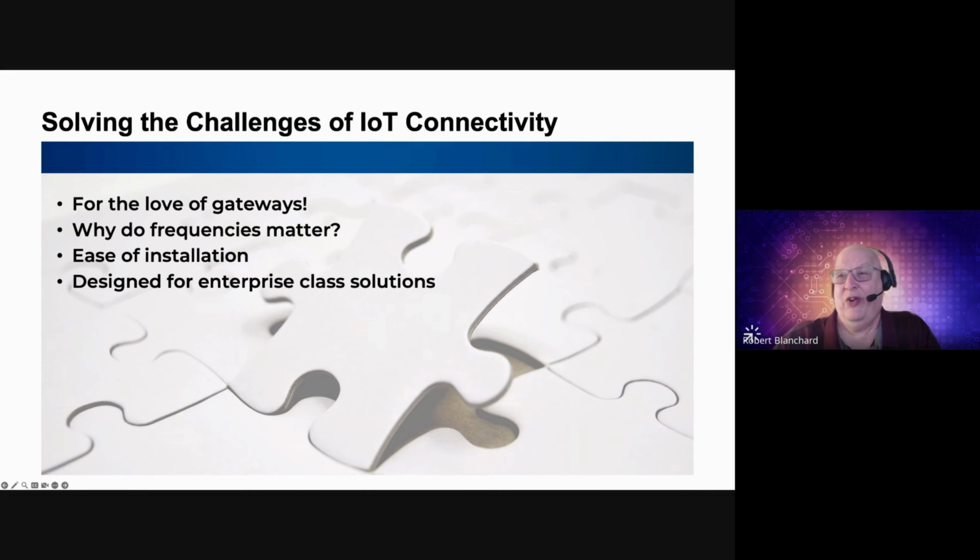You get a lot of interference. So now you're not only interfering with the customer's Wi-Fi network, but you're also degrading the quality of data being delivered by your sensors because of interference problems. But Amazon Sidewalk provides protocols that allow you to dip below those crowded 2.4 gigahertz frequencies, for example, and operate without interfering so much, which again is a big win when you're talking to the IT staff that's going to have to support those types of solutions.